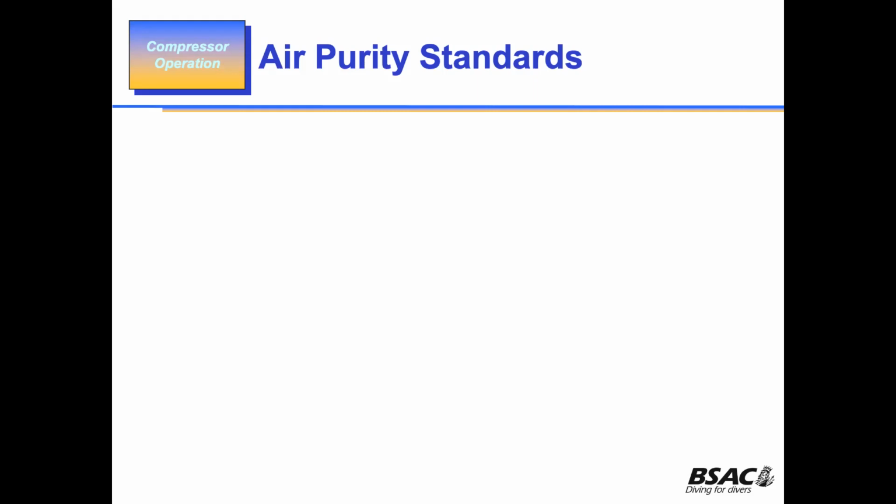Depends how you run it, right? And depends how you leave it after you shut down. But normally, if it's 20 hours, you'll probably get 20 hours. You might get 40 fills out of one filter, 12-litre cylinder. Because it also depends on how many cylinders you're filling and how long you're filling.